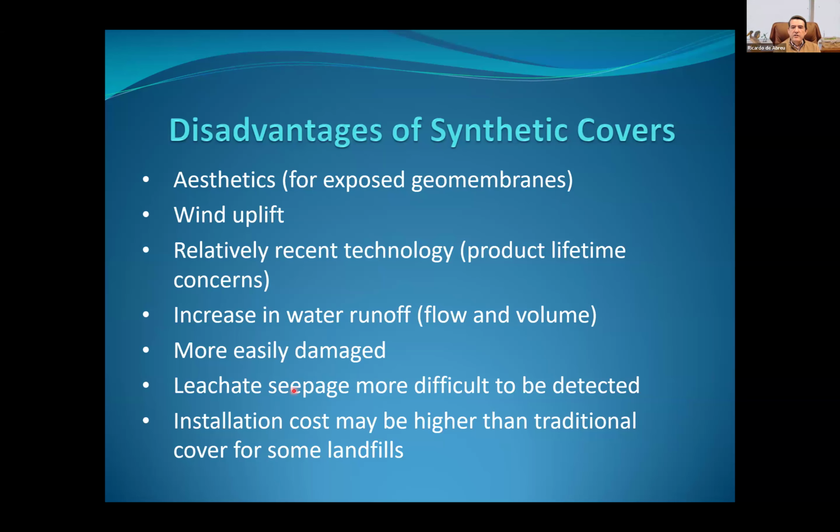So you have to account for that in your stormwater drainage. More easily damaged, since some of the synthetic covers are going to be completely exposed. Leachate seepage is also more difficult to detect, which is a concern for some people.